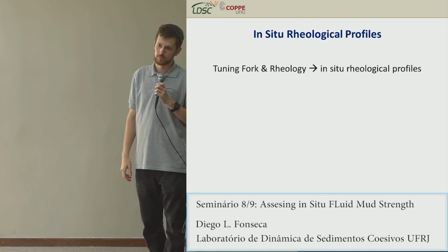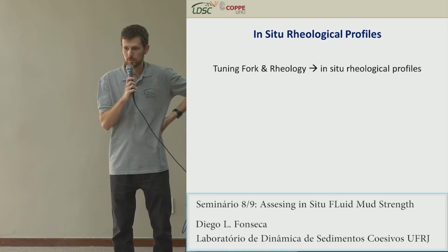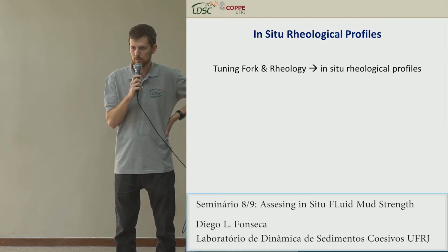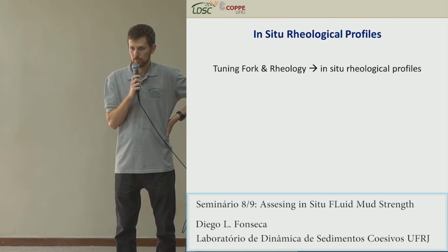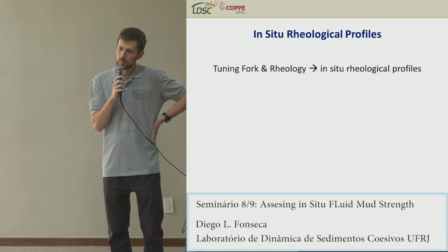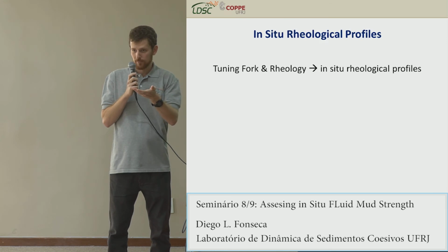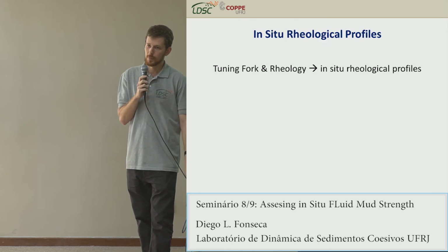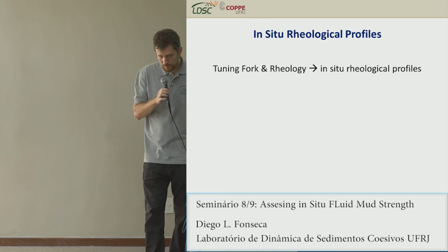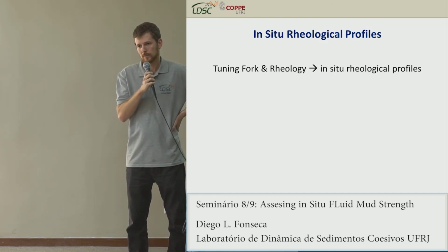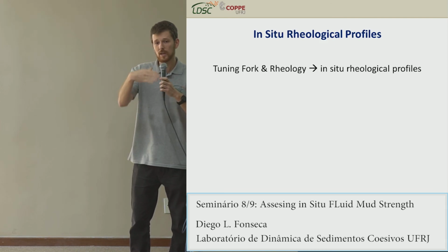And then maybe one small comment: at a certain point you showed two vertical profiles where for a certain sample you saw a densimetric jump, so a lutocline, but you didn't see any yield stress at that depth. It's something that we also saw in Zeebrugge, that at a certain depth you didn't have a yield stress yet, but the density already starts to increase. But then you made the claim that this has no implications for nautical accessibility. I think you have to be careful there, because just the fact that you have a lutocline can mean that you get an internal wave, and that can have